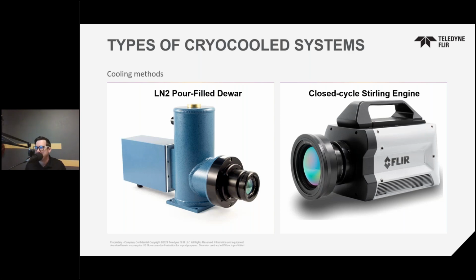You don't really need to understand how these cameras operate at a low level to get the idea that these are much more sensitive than the bolometers. With these detectors, we're detecting changes at around 0.02 Celsius, so exceptionally small changes. Not only that, but the electronics packages typically built around the detectors enable a user to access low-level settings to optimize them, and it's because of this aspect that most spectral filtering is done with this type of detector.